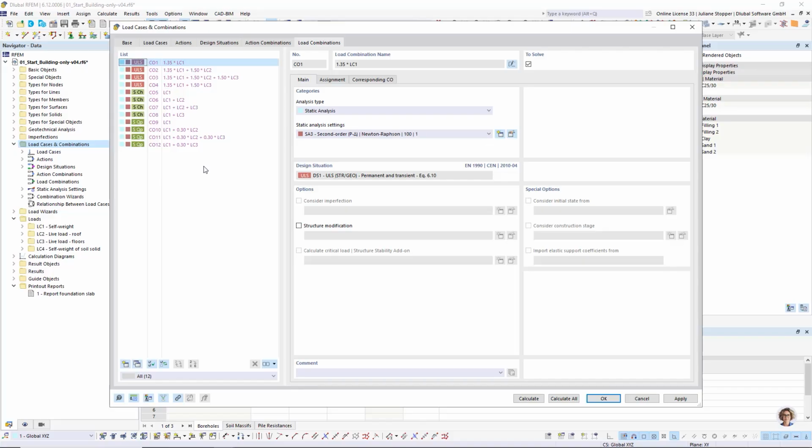So we have this here, the advanced half-space method, in RFEM 6, and this will be done for every load case you solve or for every load combination. This is the default behavior. If you calculate any combination, it will just use the advanced half-space method, and it will calculate the corresponding foundation coefficients for every load situation, for every combination.